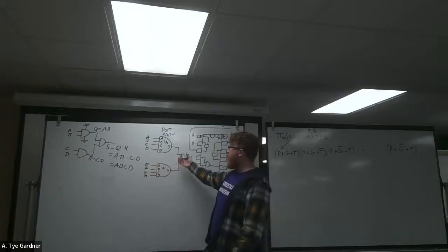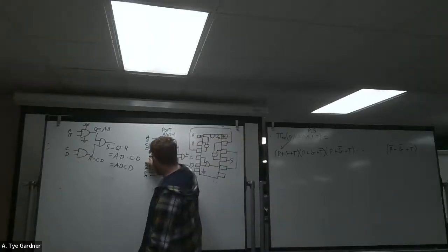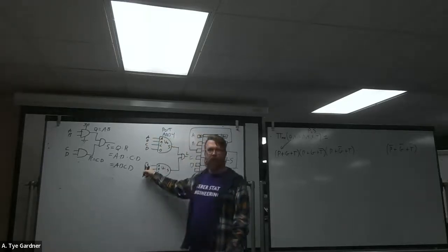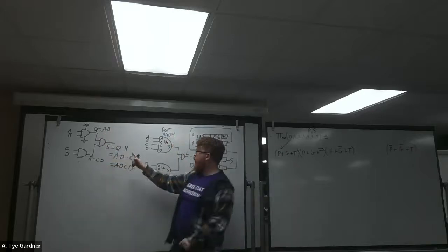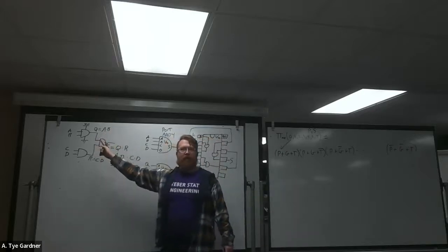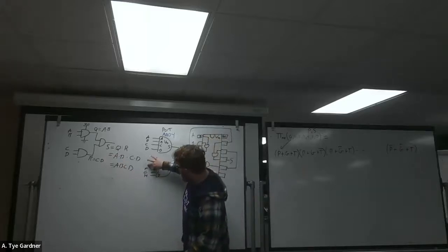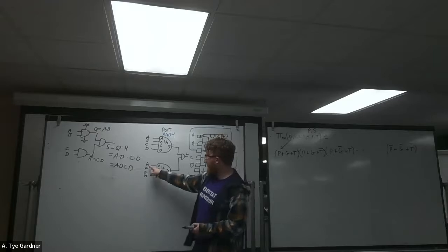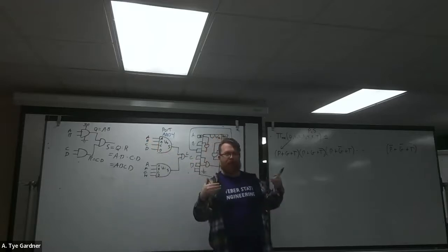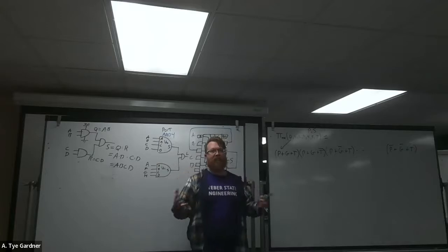And you can just prove yourself with these internal signals. Well, not prove, but I want to really illustrate. If I call this Q, that's fine because this Q is internal to the 4 input gate. It doesn't know that there's an outside Q. However, if I called it A, I have a problem because this A and that A are the same level, they're the same part. And that means this A and that A are now connected because they have the same name.